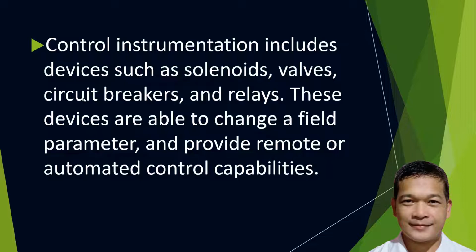Say the temperature is sensed using the LM35 temperature sensor. Whatever heat is sensed by the LM35 is converted to electrical form, processed by a microcontroller, which gives instructions to the actuator, or to the device that will do the control of the temperature.